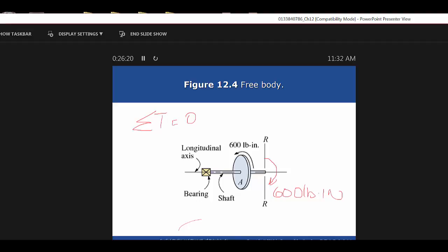If you twist something hard enough, you can twist it in two, can't you? In fact, a bolt that's locked up, that's rusted, you keep twisting, and sooner or later that thing just spins apart. That's torsional shear. Another case of that, what else? Where else does that happen? A piece of wire. Yeah, but that's more of a fatigue type thing, I think. Depending on how ductile the wire is, you start getting into some other material sciences. So the bolt is about the best one I can think of right off the top of my head.